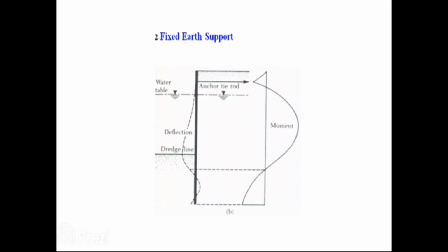And for the next image, we have the fixed earth support method. The piling is driven deep enough so that the soil under the line of excavation provides the required restraint against deformations and rotations. In short, the lower end of the piling is essentially fixed.